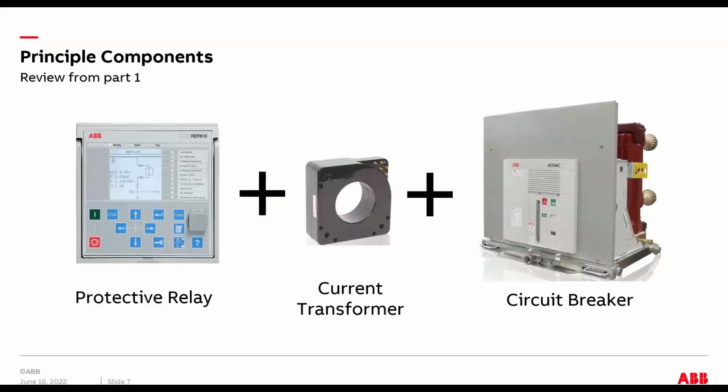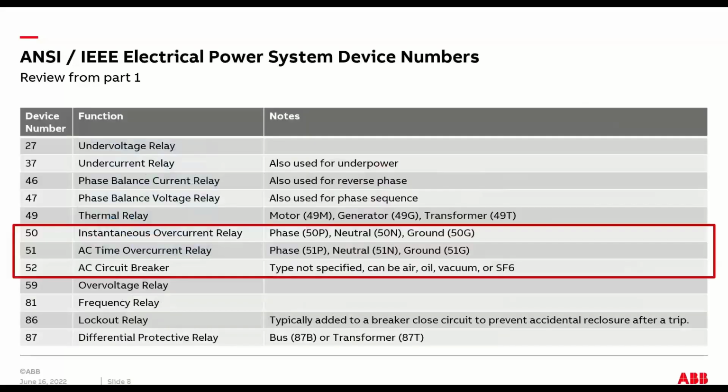So the point is, the onus is on the engineer to specify each component correctly and make sure that they work together as a system, and then understand what the dynamics of that system are, what the limitations, time delays, all that information. So a lot more engineering up front takes place in the protective relay / medium high voltage world than it does in the low voltage.